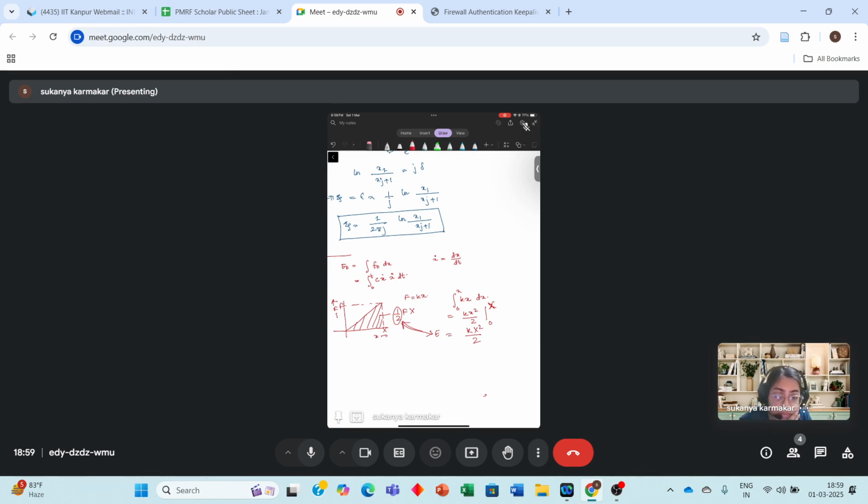This is in relation to the Coulomb damped free vibration. The displacement amplitude diminishes with a coefficient of 4 times F by k, isn't it? True. So, ma'am, one assignment question was there, where the initial amplitude was given as 200 mm and 4F by k is coming to 25.3 mm. So the initial amplitude is 200 mm.